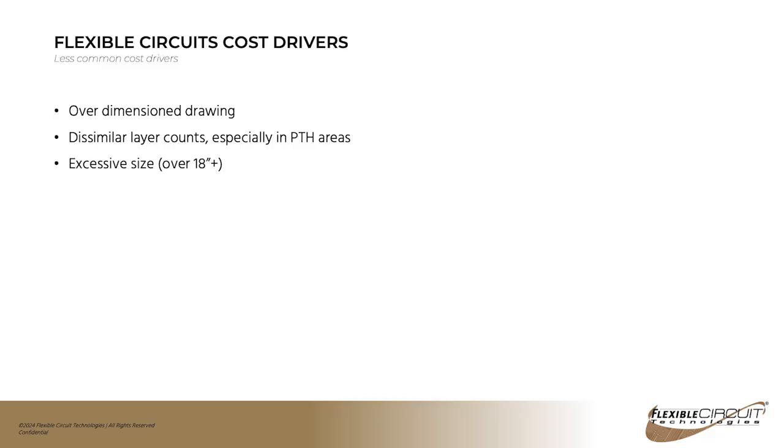If you have a large circuit, it's going to have an impact on the cost up and beyond just the size of the footprint that it's taking up on the processing panel. As I mentioned earlier, manufacturers have standard panel sizes, and if your part does not fit on that standard panel size, it's going to require some significant changes in their processing in order to build a part, and that's going to definitely have an increase on the cost of the circuit.